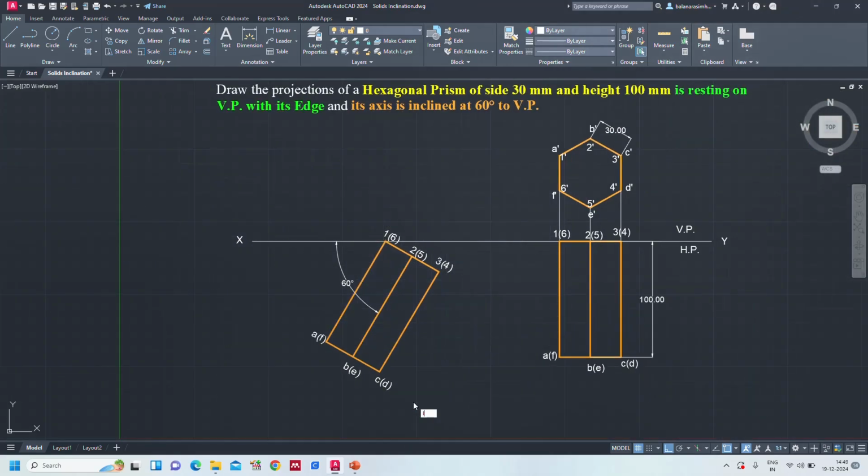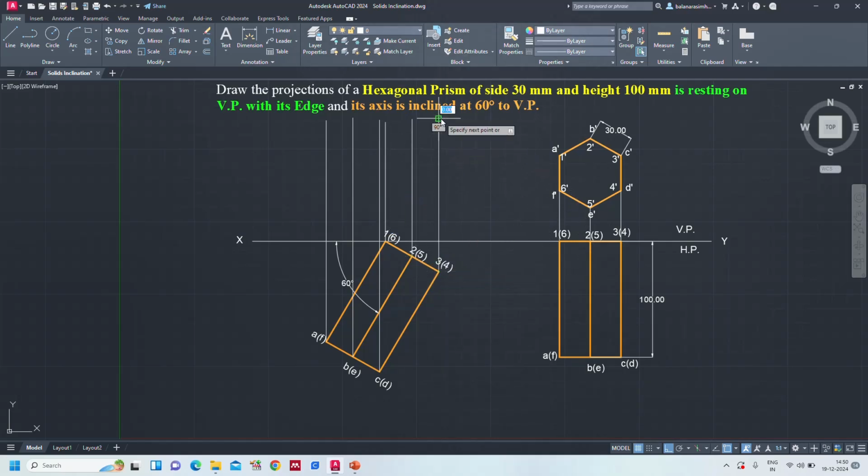Okay, now it's time to construct the final front view. So draw the projectors for the front base. Okay, and now draw the projectors for the back base or rear base also you can call it as. So the vertical projectors got finished, and now it's time to construct the horizontal projectors. Okay, trim.